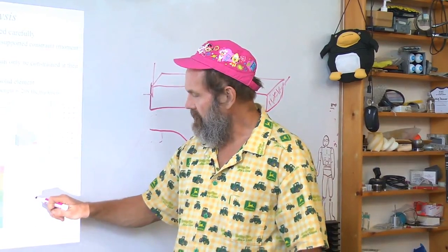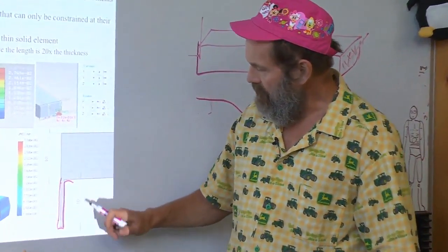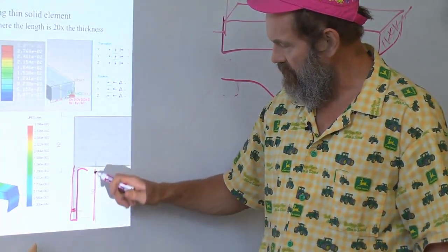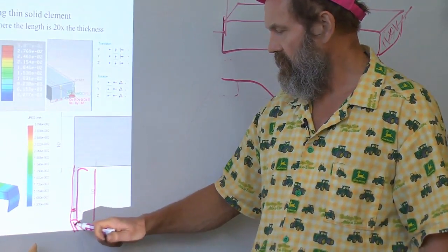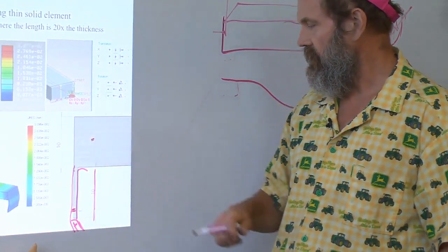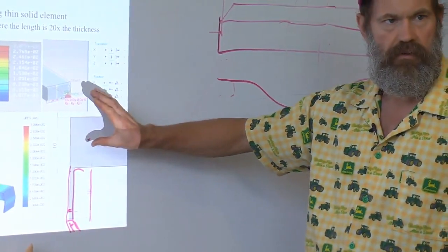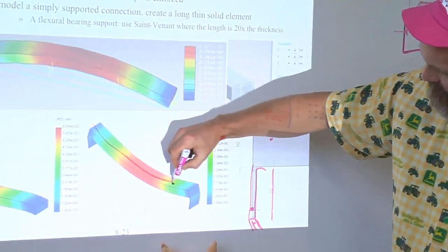So I can add this little tab here. But notice the proportions. This is 1 unit across. This is 10 units tall. So St. Venant says that if I anchor this here, this will not be able to affect this structure here with respect to bending. It will only provide vertical support. And now you see that I'm getting the actual shape of the structure.